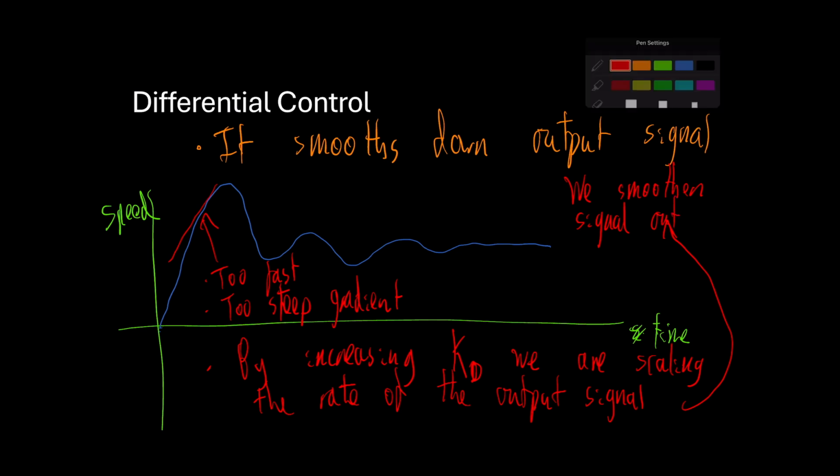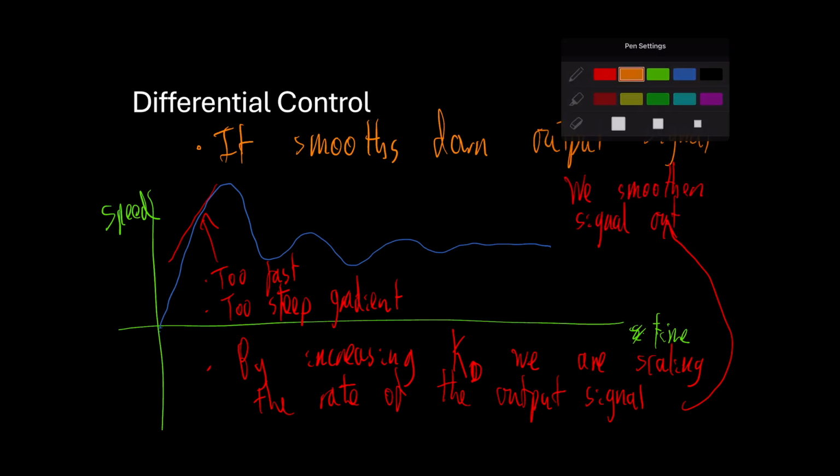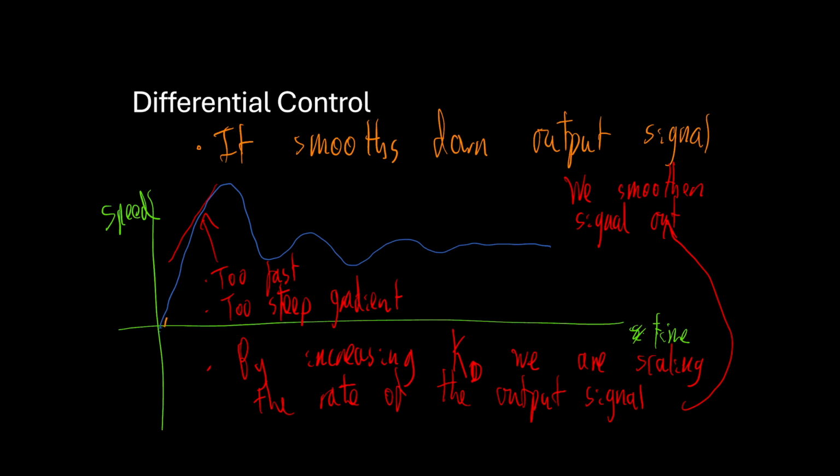Because KD has been applied, I'll draw that in orange. We look at that and say, well, actually that is too steep. So what KD does is it smooths it out. Of course, it's good at removing the oscillations too, and that's typically how KD would work. Now, that line is not exactly what it would look like, it's a bit high up, but the point of KD is it removes this oscillation and removes the overshoot.